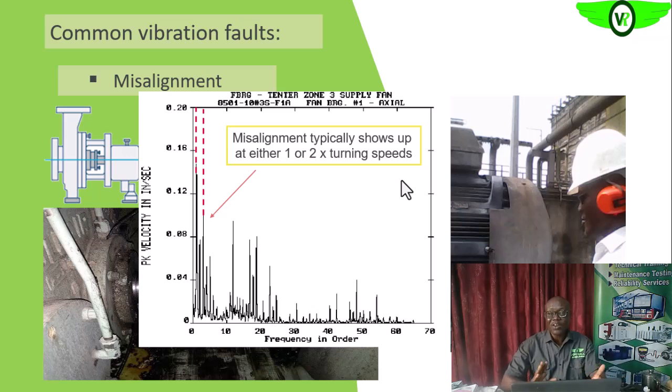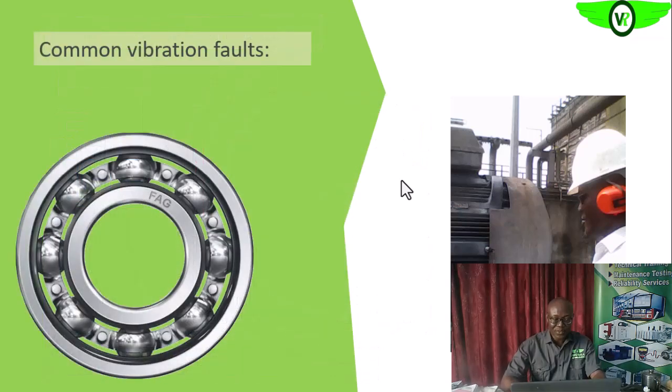So if there is confusion as to what is actually causing the problem, then you can do your phase analysis as we have explained earlier. Then you'll be able to confirm that yes, this is a misalignment when both signals are 180 degrees out of phase.